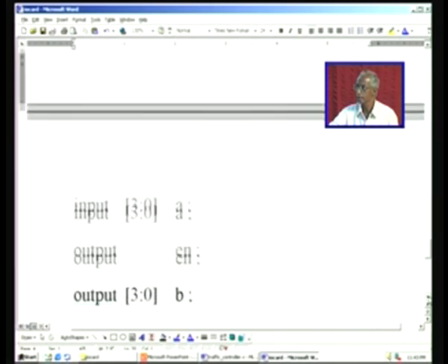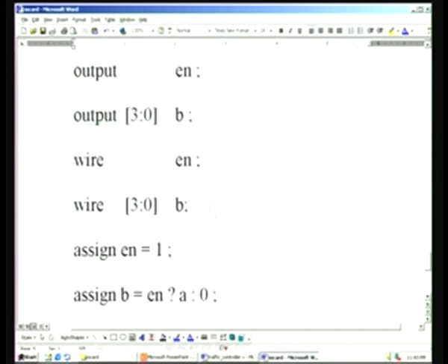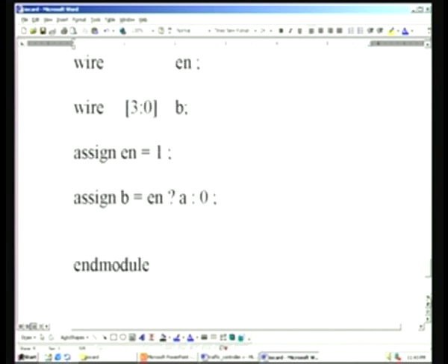In the code, once again, the input output declaration is here, and we have put only 4 bits here. For as many bits as you require, you will have to put that many, and for a 4 bit binary switch, 4 is enough. If you have multiple, accordingly you have to increase this instead of 3, as many as you want. We are going to use only assign statements, therefore they are declared as wire here, and 2 simple instructions will do the trick.